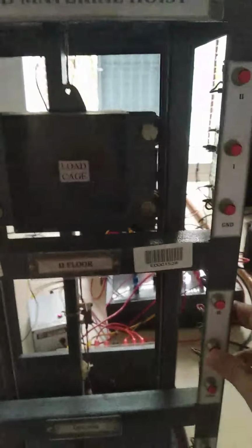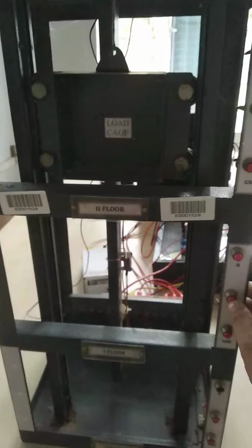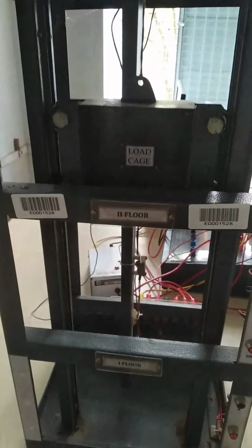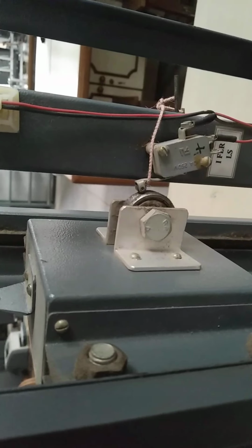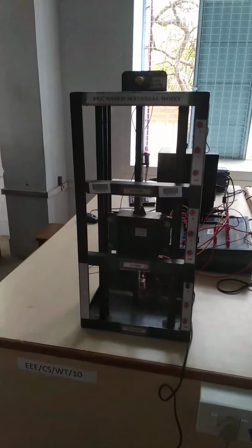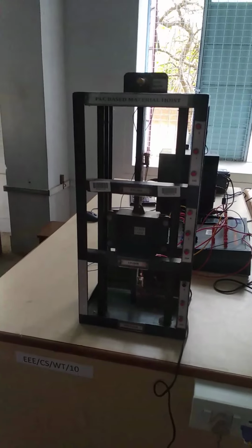Now if you give the input to the system, then it has to work. Let me enter the first floor. I want the hoist to come to the first floor. Now what happens, the motor is reversing, rotating in the opposite direction, and because of that the hoist is coming. And also look here, exactly when the limit switch is activated, the motor is turned off as per the PLC program. So I hope this particular experiment gives some insight on the basic operation of the PLC as well as sequential control. Thank you.